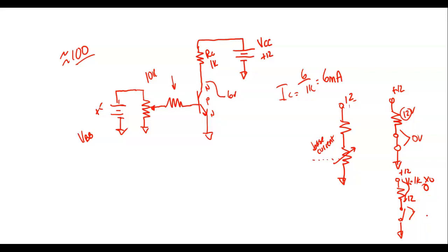So in a series circuit, the entire voltage appears across the open. If I came over here and measured across these wall light switches, what would they measure across the switch? 0. Because why? They have no resistance, even though these lights might be pulling 1,000 amps, which they're not.